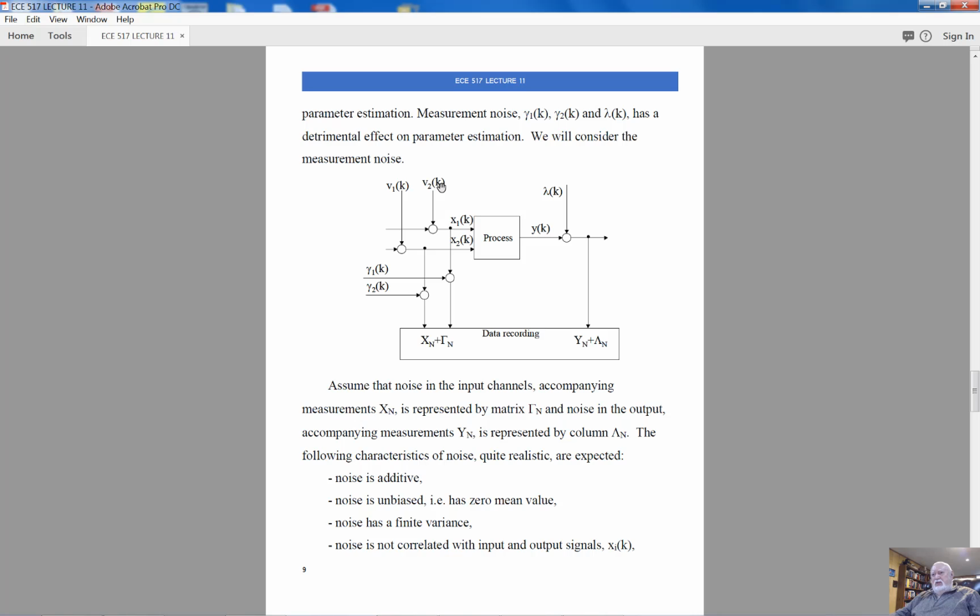You can call them noise. By their statistical properties, it could be white noise or Gaussian noise, but one way or another, they will result in the increased variability of the output of the process y, and they will enhance the estimation process. But at the same time, I want you to realize that these input signals, x1 and x2, including this noise component or not including this noise component, are measured and recorded.